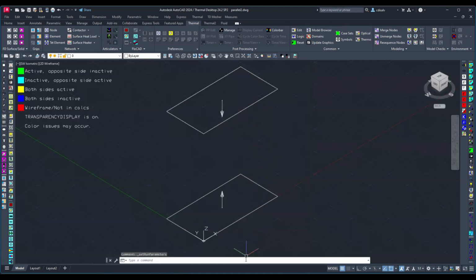And now we go to the scale, LT scale. We're going to set that to 0.5. This sets the scale for our lines, defining our segments on our surfaces. And if it's going to be a much larger piece of geometry, then we go with a bigger value, but 0.5 will be fine for this particular geometry.